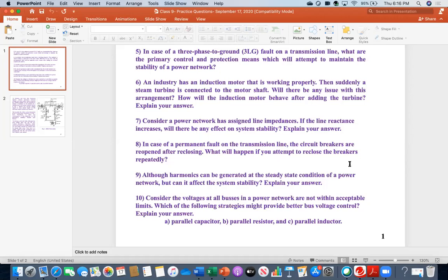So that's why I said that in Japan, I have noticed they have programmed it in such a way that after reclosing, immediately their system will understand, okay, there has been something wrong. It is not a temporary fault, it is a permanent fault. Whatever the reason, whether it is a tree or something else, then they don't attempt a second time. So what they do, they immediately send the engineer, and if necessary, they shut down the power in that area, and then they take quick action.